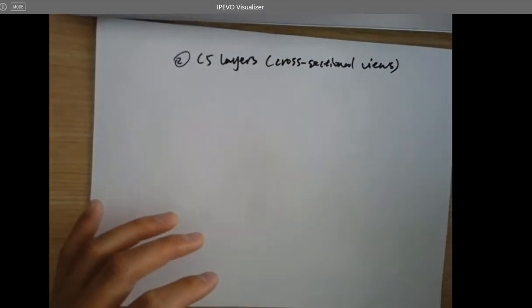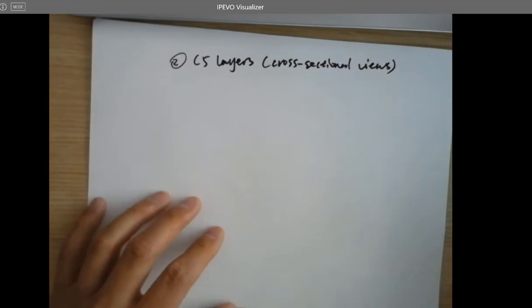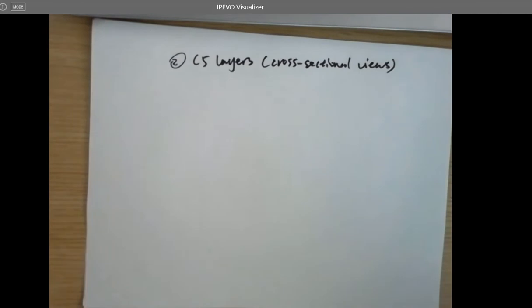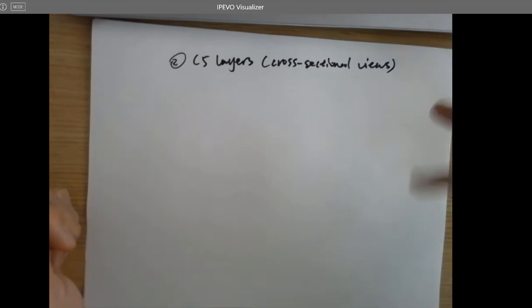I directly probably will grab a snapshot from any of the layouts in the lab reports or the lab instructions. So you'll see a colorful picture with a layout. It can be a multiplexer, it can be a transmission gate. I'm going to randomly draw some of the dashed lines on top of the top view and ask you to draw the cross-sectional views. So that can involve all the metal layers and all these N+ active layers, right?